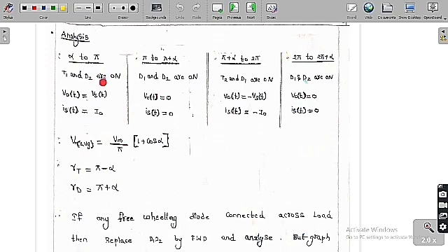So from alpha to pi, I have already told you we are going to trigger T1 at alpha. Therefore T1 and D2 are going to conduct in the alpha to pi. As T1 and D2 conduct, the output voltage is equal to the source voltage, and also the source current is equal to the load current, so this is equal to I0.